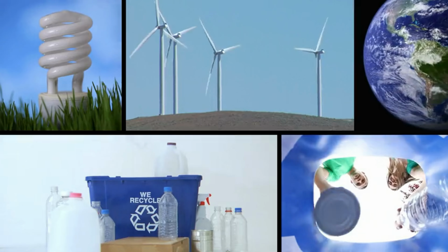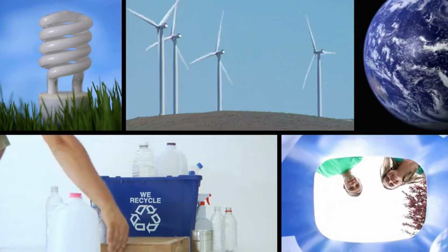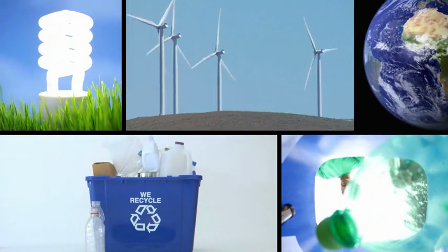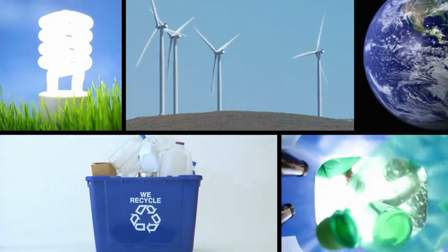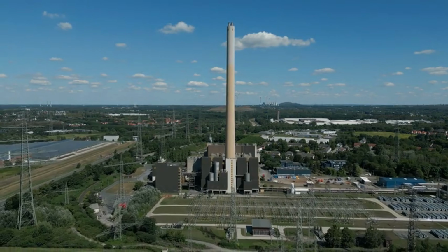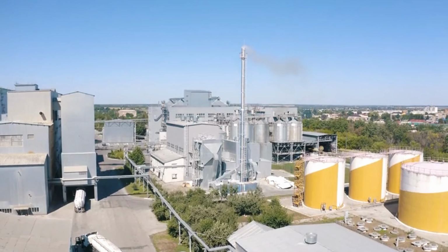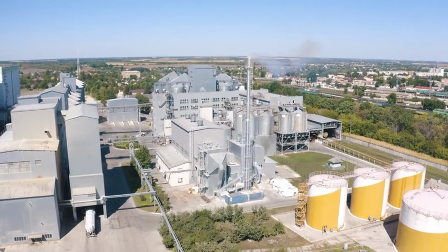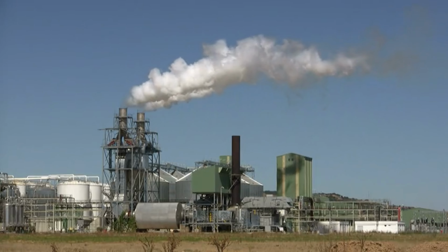7. Environmental sustainability in modern mills. A. Water and energy efficiency. Closed-loop water systems recycle up to 90% of processed water. Energy recovery from black liquor supplies 60 to 80% of mill power. B. Carbon-neutral paper making. Biomass cogeneration replaces fossil fuels. Carbon capture projects are being developed.